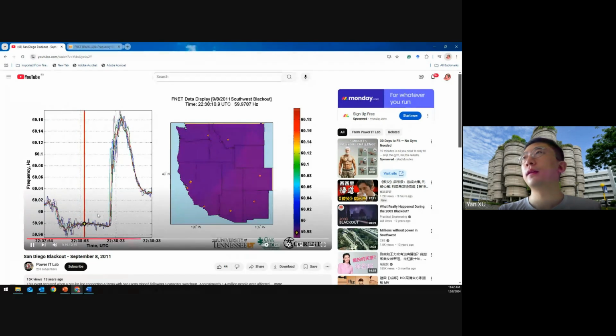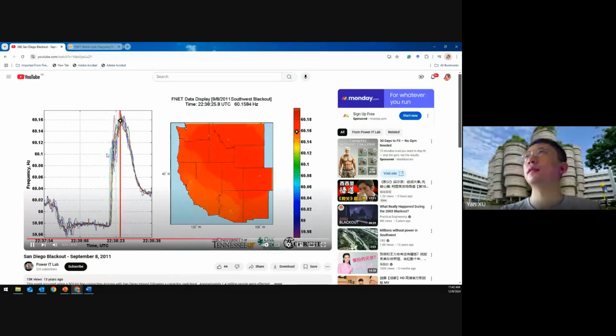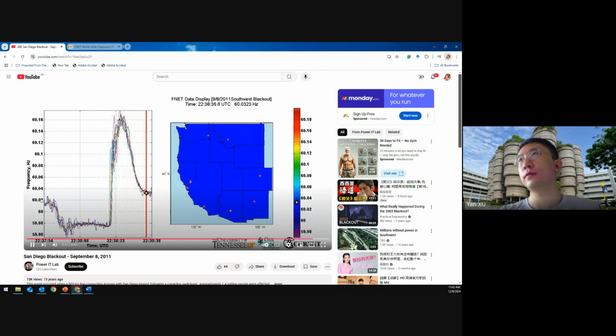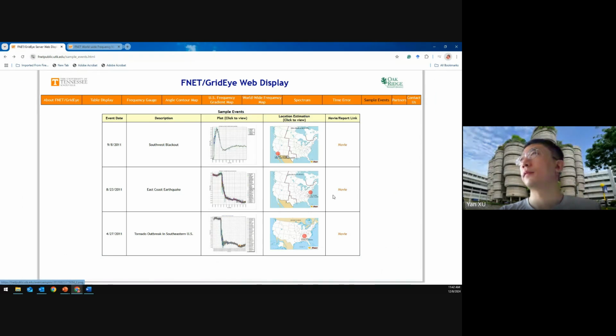Then it stays at this low level for maybe longer than 10 seconds. After that, the protection has triggered. It may cut off some load, shed some load. Then the frequency starts to recover immediately back to 60. After that, system primary control has also acted. Then the frequency finally recovered. This is also measured by PMU for the frequency.